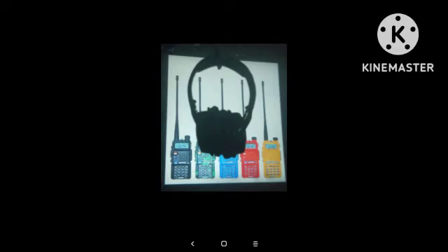Number 32. If you install a 6-meter Yagi antenna on a tower 50 meters from your transmitter, which of the following feed lines is the best? RG213. Number 33. When antenna feed lines must be placed near grounded metal objects, which of the following feed lines should be used?